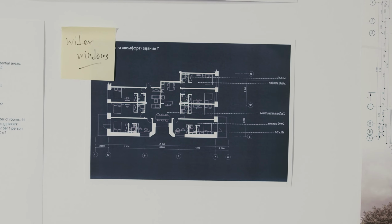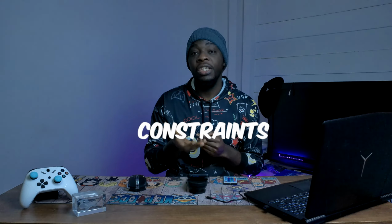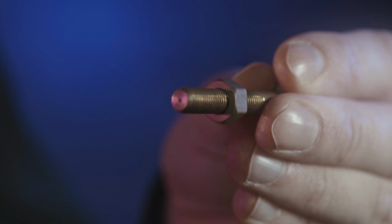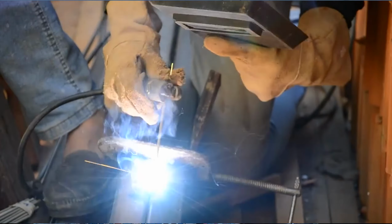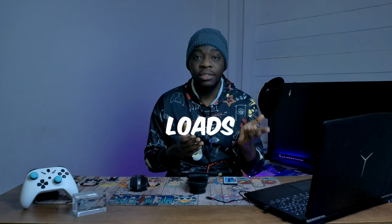Next, we need to consider the geometry of the part. We need to consider the dimensions of our design and the material properties as appropriate. Next, we need to have constraints. We need to have an understanding of how the system works with its surroundings. Is it bolted? Is it welded? Is it sliding? Is there contact with other parts? Those things need to be considered. Next, we need to have loads. These are the magnitudes, and we need to know how much should be applied on each part.